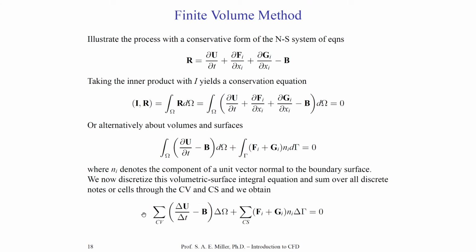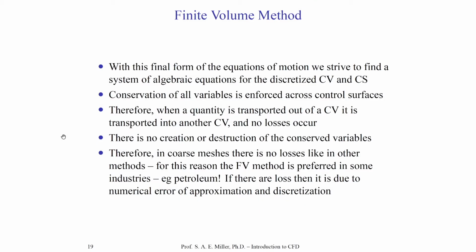You can now see we are formulating a summation over every volume element to form a system of equations. This is really the final form of the volumetric approach, and it's the simplest approach of all. Perhaps you do understand and prefer the finite difference approach more, but this is really a personal preference. Many students getting into CFD for the first time prefer the simple approach.